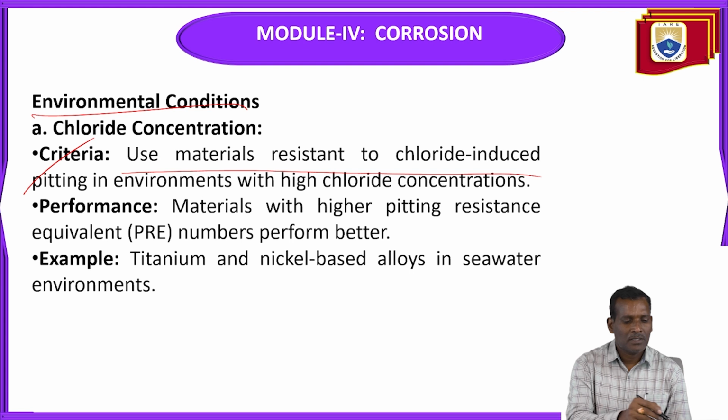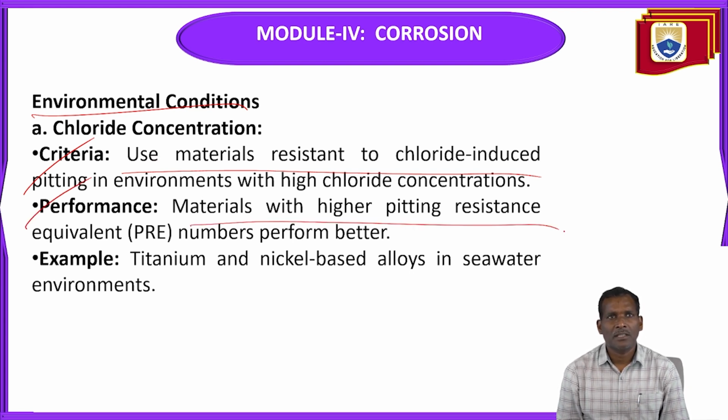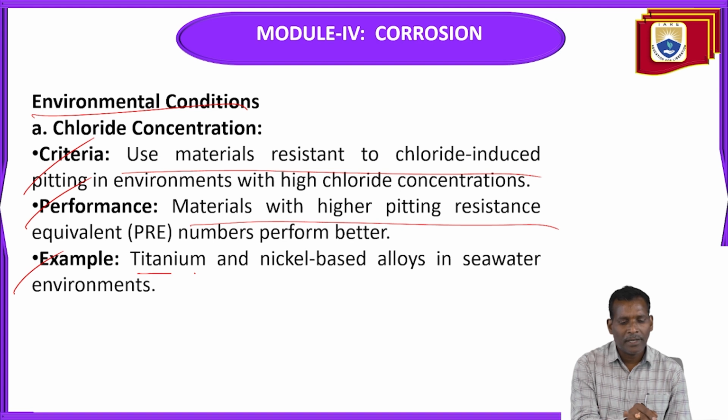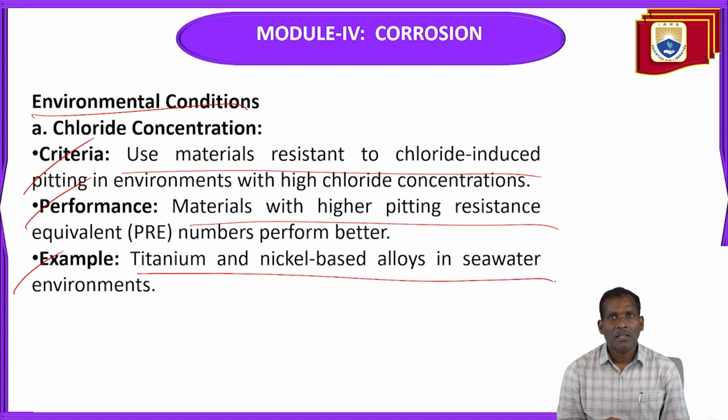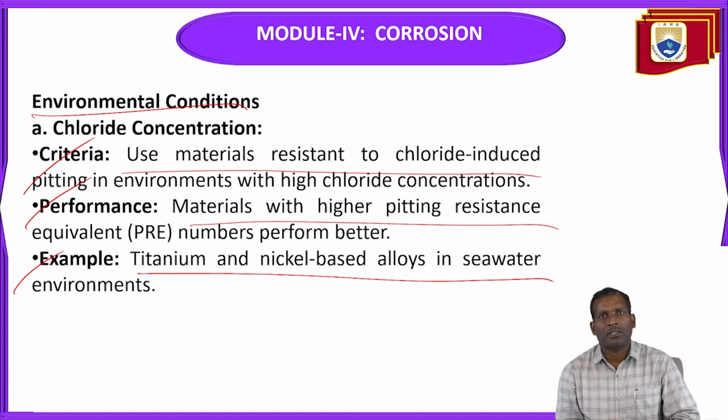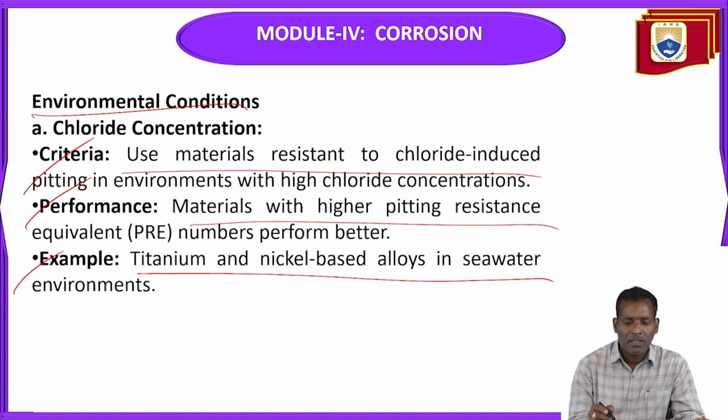Materials with higher pitting resistance equivalent, PRE, numbers perform better. Examples are titanium and nickel based alloys in seawater environments, which we have already discussed.